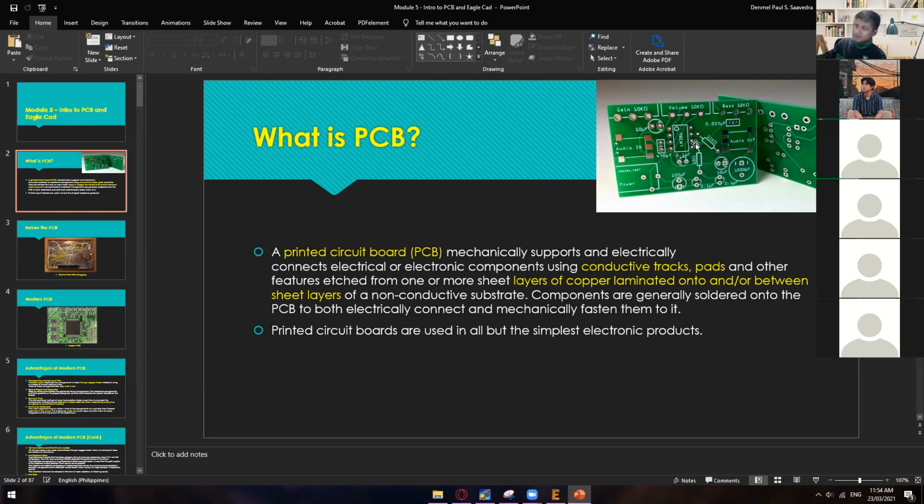So this is one simple PCB. Okay, so we have here the front and then the back portion. Okay, so mostly we are designing our PCBs on the top side. Okay, and then if we can't really route it on the top, then that's the time that we can route it on the bottom. So as you guys can see right here, this one line and another line right here are on the bottom part of the PCB itself, or the circuit board. All right, so in total you have printed two, PCB on the top and PCB on the bottom. So those two are different designs.